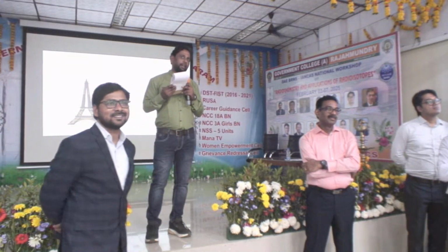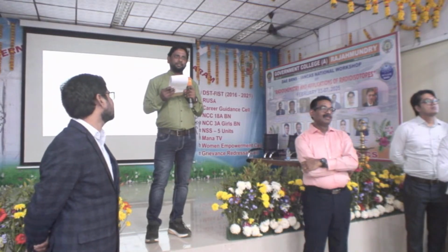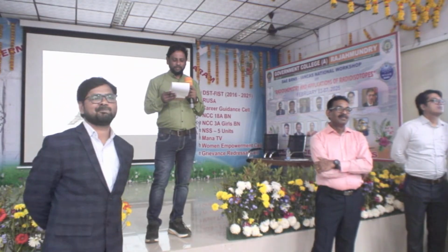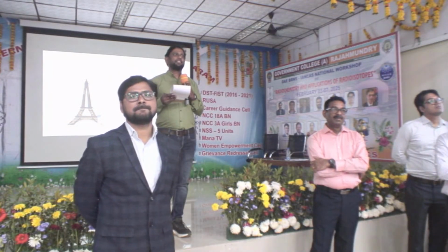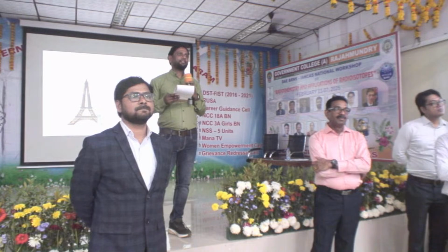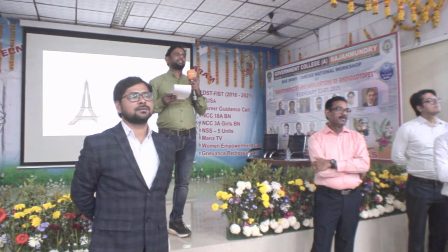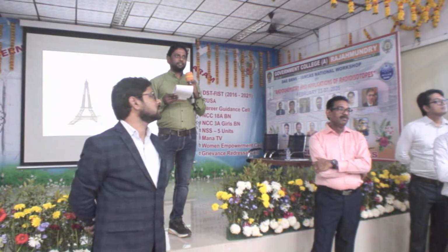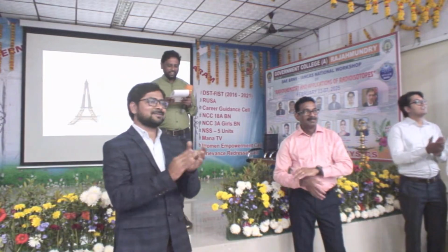Coolant doesn't need a melting point. High thermal conductivity and nuclear stability. Next, anyone? High boiling point, high specific heat, high thermal conductivity, low viscosity. Yes, very good answer.